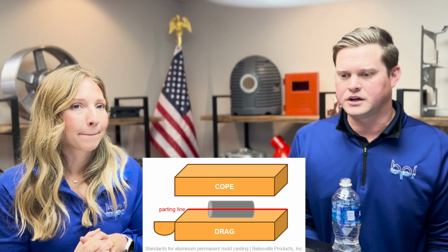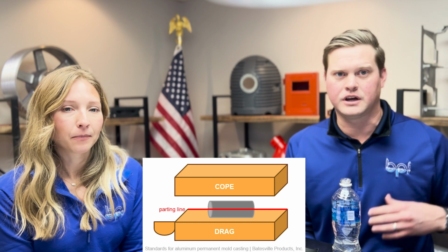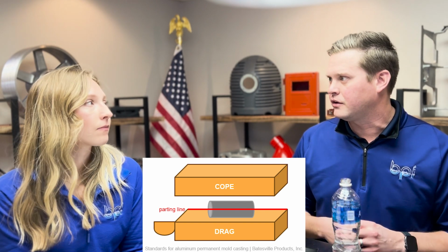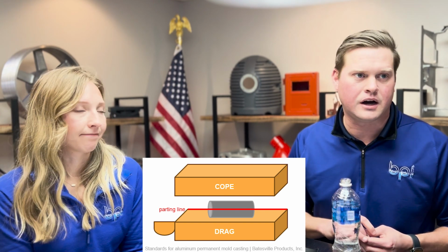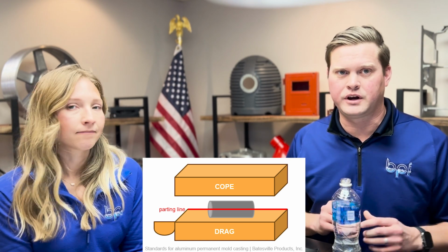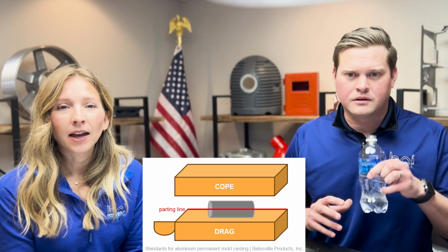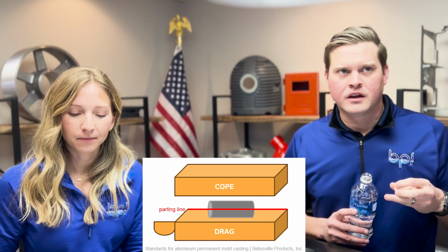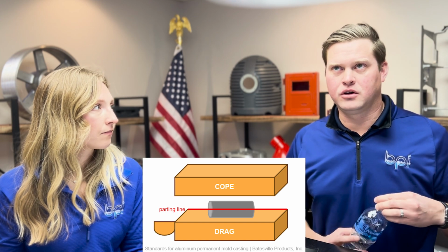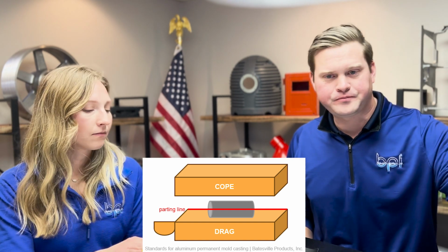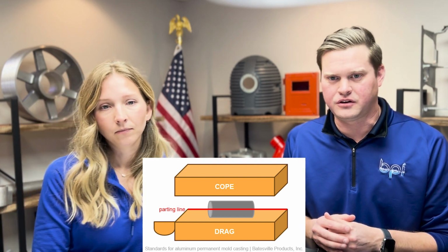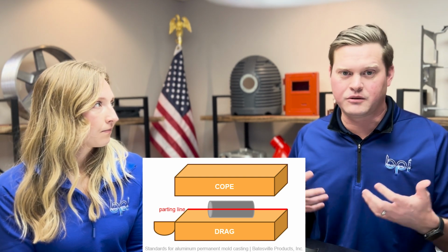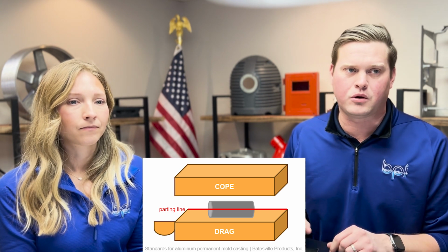It's important to try to work it out where it's not in a critical area. Yep. If you've got a design feature that you really need in your end product, we don't want to put that parting line there, because typically it gets blended in a polishing op. Sometimes it doesn't, but you definitely want it in an area where it's not on a critical feature. Yeah, and again, there are always secondaries to remove the additional draft that's added to help the part eject from the mold. And I would say with a good caster, they'll help you walk through where you should do it. They really interact with you, the end client, and understand your needs. But from a casting expert side of things, they help you understand what's needed to make sure we're getting the end goal in mind of a great casting with great quality coming out of the product here.